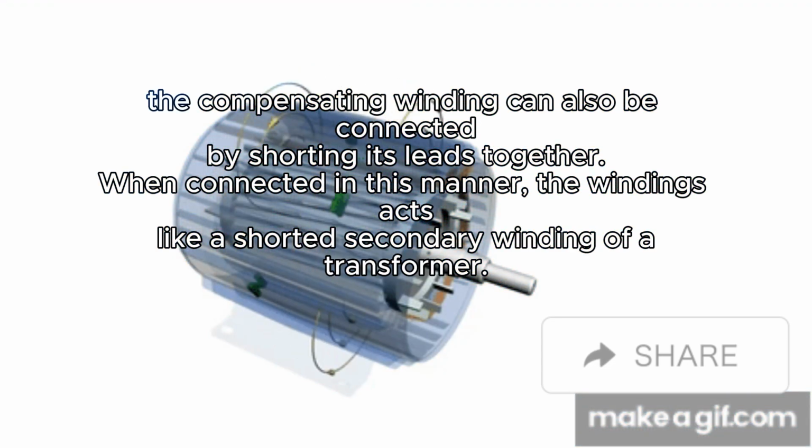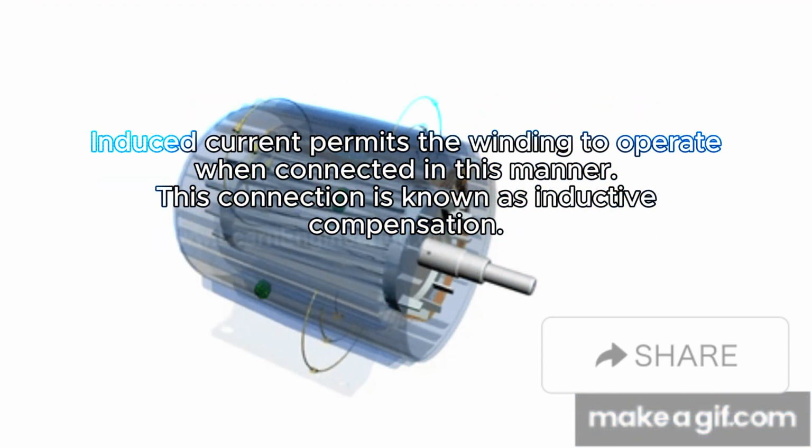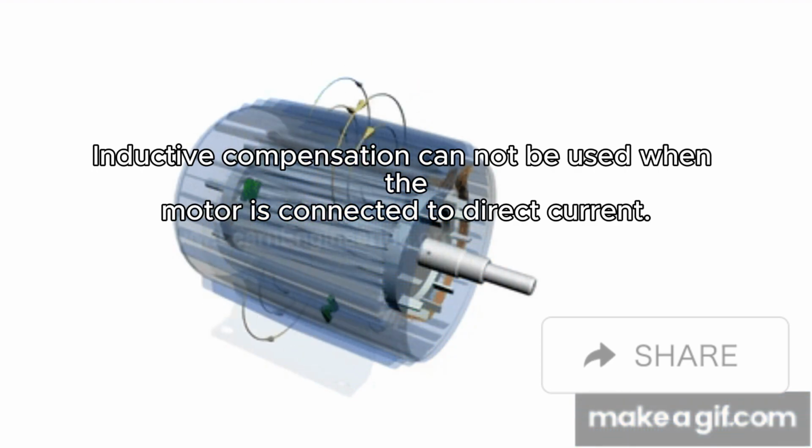When connected in this manner, the winding acts like a shorted secondary winding of a transformer. Induced current permits the winding to operate when connected in this manner. This connection is known as inductive compensation. Inductive compensation cannot be used when the motor is connected to direct current.